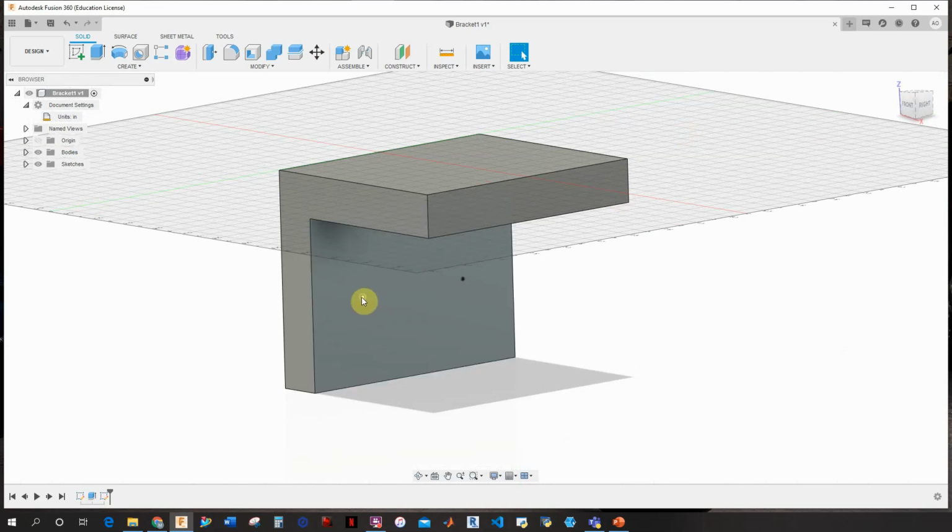And now I have those 2 points within that sketch that I can select as locations for the holes. Also notice that before the points were white, whereas after I define them, they turn black. That's similar to the blue or black lines in sketching. Once they turn black, that means those points are fully defined, fully constrained.